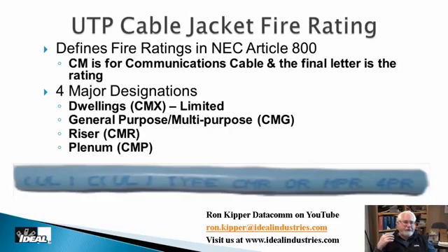And if the wire is going to be run in those kinds of areas, you have to run plenum. And that is probably one thing that your inspector will definitely know is out there in the field. So be looking for that on the cables as well. Very important one to know.